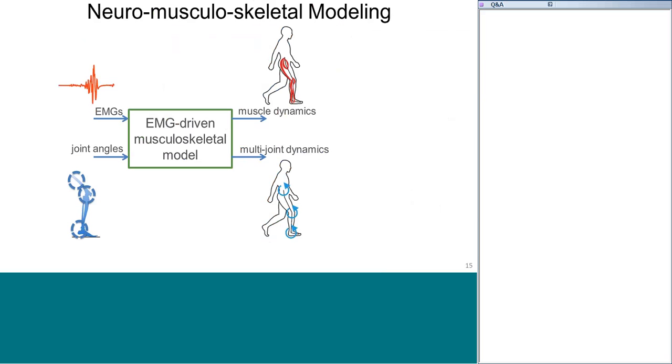So using EMG data as an input for our model, we can predict output variables that can be useful and effective in the implementation of control systems in exoskeletons. In this context, we would need up to 16 electrodes to cover the major muscles in the lower extremity and to cover the major degrees of freedom.